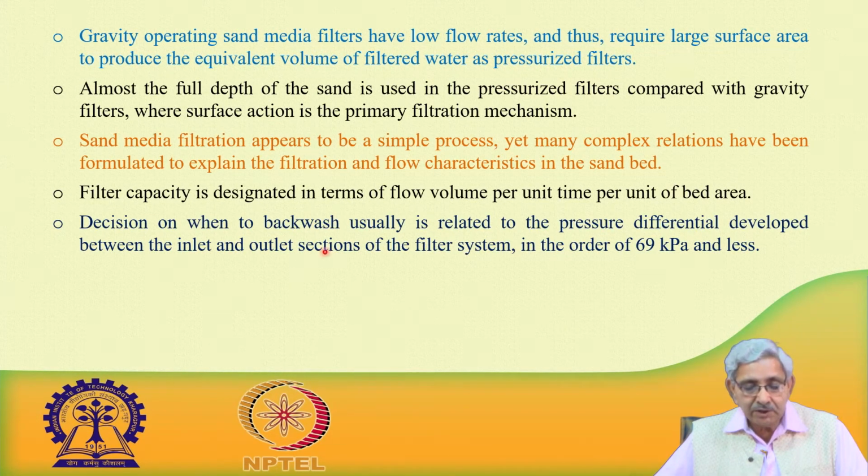Sand media filtration appears to be a simple process, yet many complex relationships have been formulated to explain the filtration and flow characteristics in the sand bed. Filter capacity is designated in terms of flow volume per unit of bed area. The decision on when to backwash is usually related to the pressure differential developed between the inlet and outlet section of the filter system.